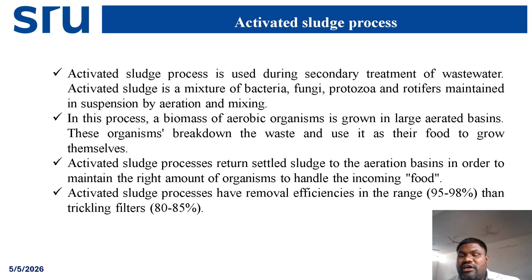Here there are two separate units: one is the aeration tank, followed by the secondary clarifier. After the primary sedimentation tank, there will be the aeration tank. Here we need to provide aeration so that the microorganisms present in the tank remain in a suspended state.